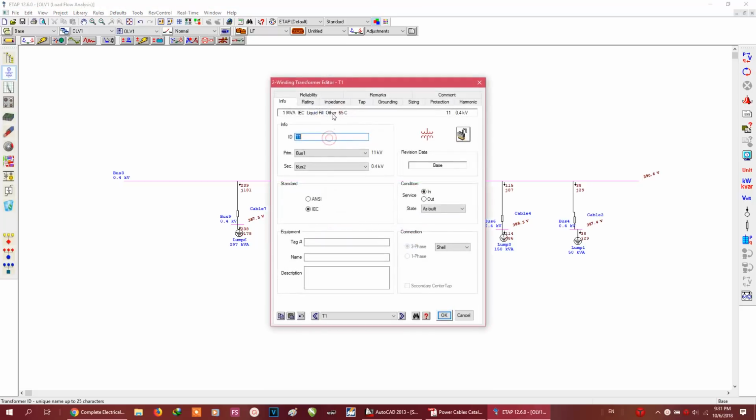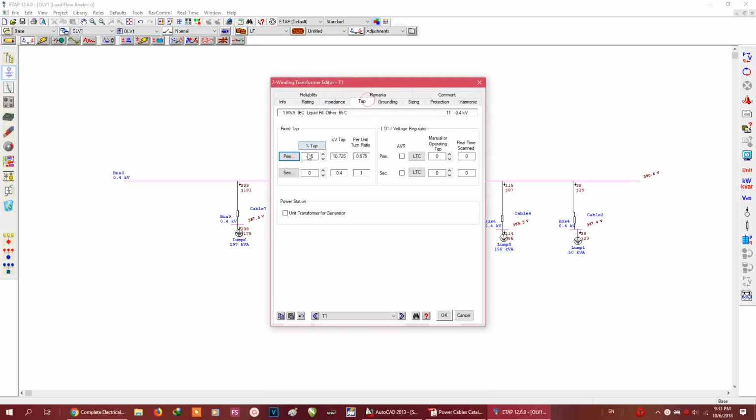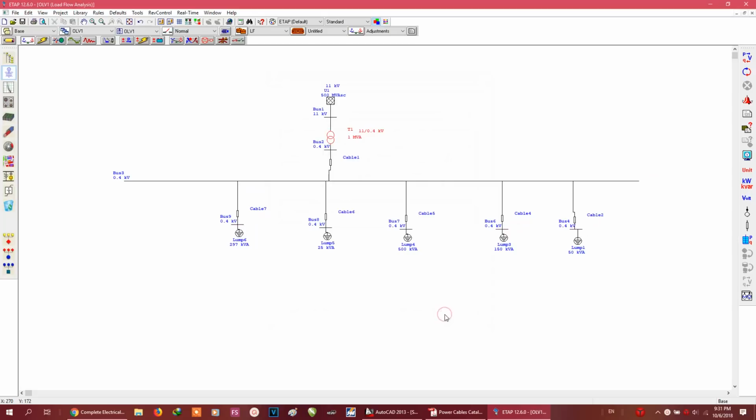The second method we can do is, let's delete this. We know that for induction motors, or for an industrial plant, the power factor must be at least 0.9. If it is less than 0.9, then you will have a penalty due to having a low power factor. Since our power factor here is 0.8, we can do something.